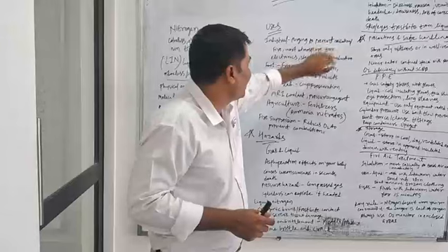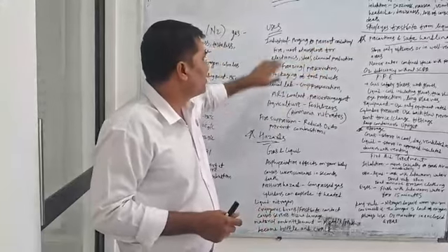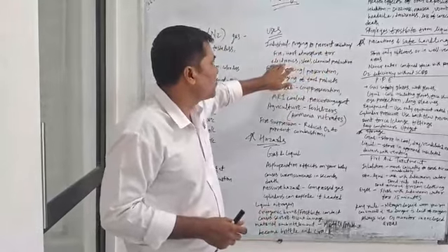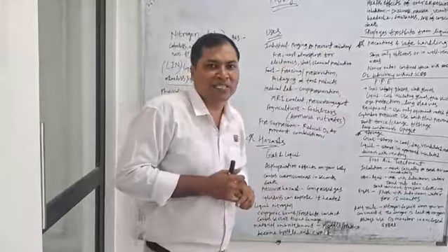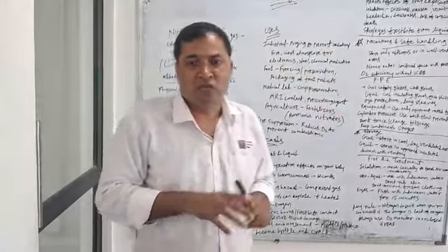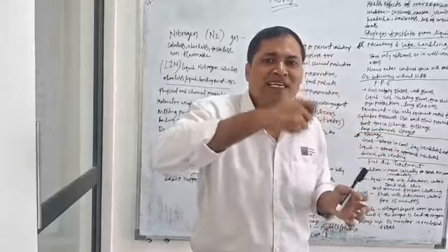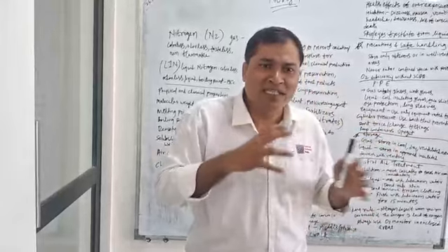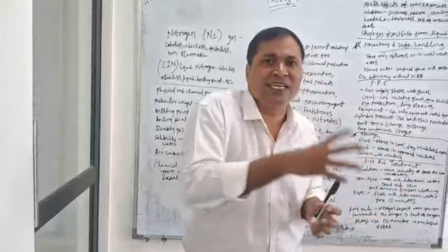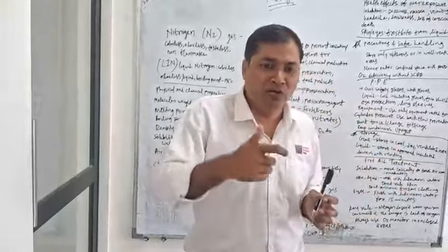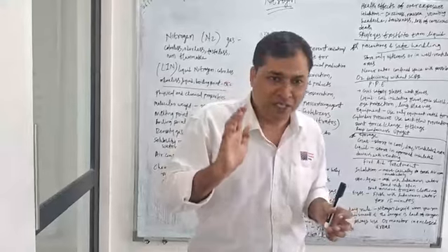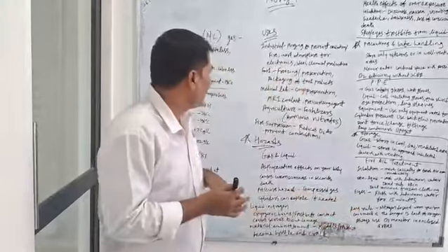Purging prevents oxidation and fire in the atmosphere, and is also used in electronics or chemical production plants. If you have to go into the pipeline for welding, cutting, gas cutting and that kind of job, you first need to purge that pipeline with nitrogen at great pressure.